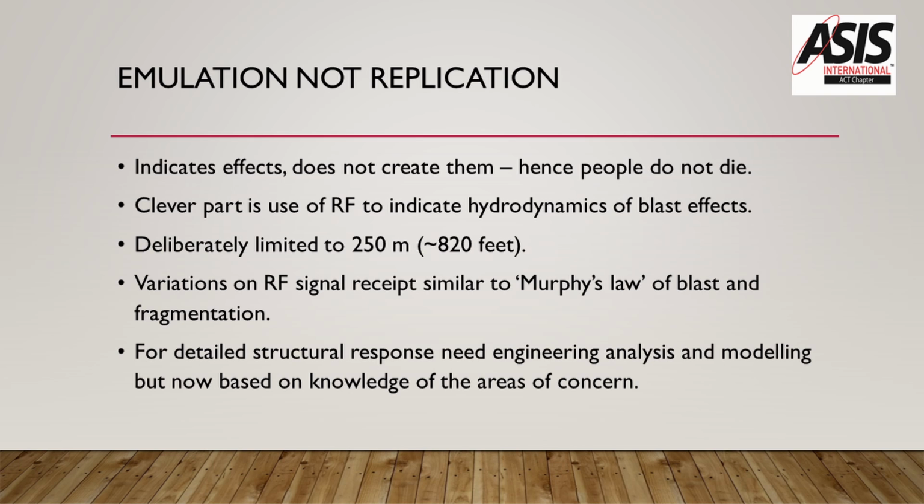The detailed structural response, the orange LED may have triggered, and that may say, oh dear, this part of the building will suffer significant damage. One of the things that we'll do is overcome the desire for people to say, oh, there's been an explosion, the entire building will collapse. Well, not necessarily, not unless we've actually taken out a couple of major structural elements, or progressive collapse was not a design requirement, or prevention of progressive collapse was not a design requirement at the time.